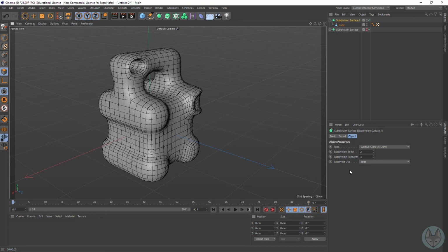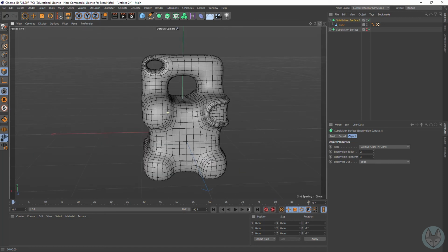And then we went in a little bit and talked about extruding polygons, doing an extrude inner on polygons, using the knife tool in a loop mode to create more geometry, and also using the bridge tool to bridge between 2 polygons and also to create a hole between 2 polygons if you go through the main mass of your object. So I hope that makes sense.